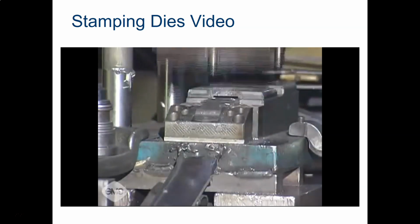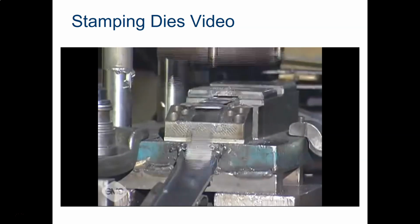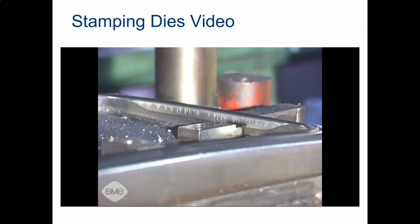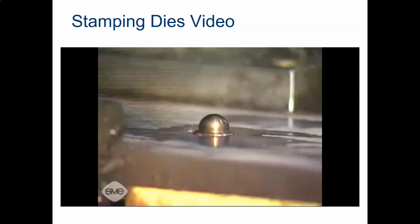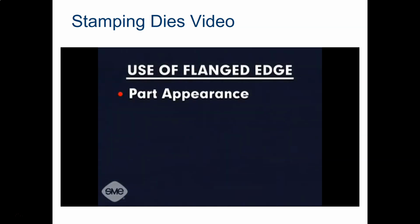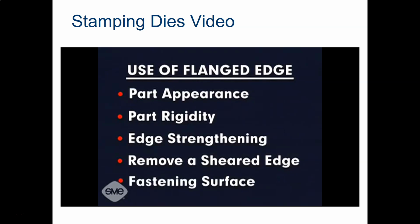Bending is usually done to make structural stampings, such as brackets, braces, and supports. Flanging is a forming operation similar to bending, except that the flanged edge is shorter and narrower compared to the overall part size. A flange can be bent down along a straight or curved line and is used for appearance, rigidity, edge strengthening, removing a sheared edge, and to provide an accurately positioned fastening surface.